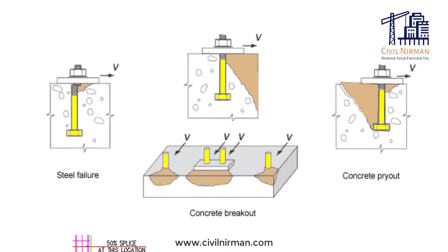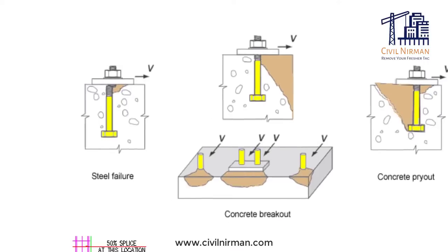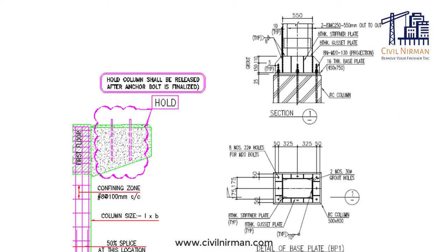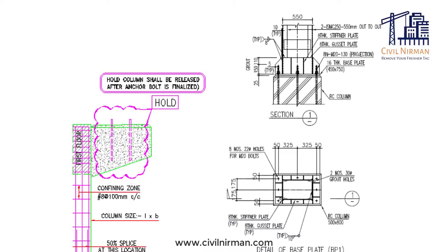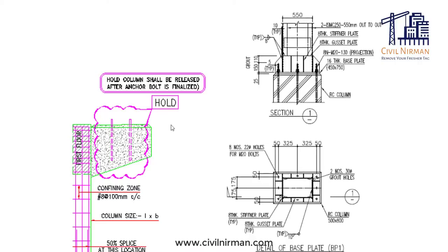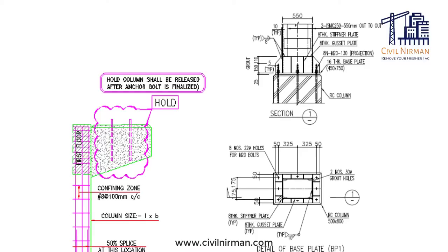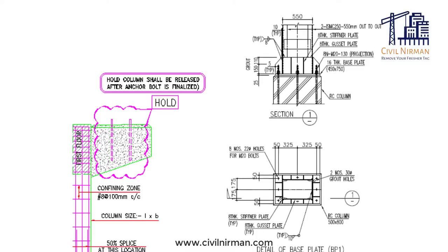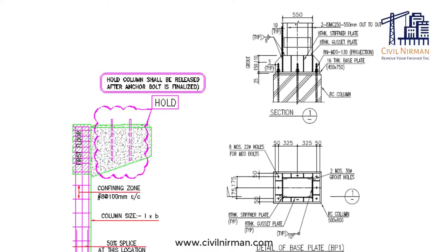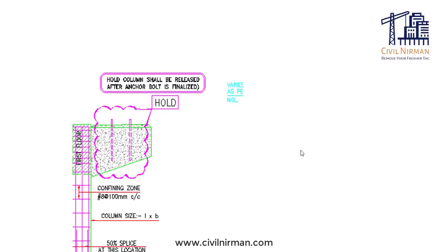So in the case of a steel structure, once you finalize your foundation design, after that you need to finalize your anchor bolt and base plate as well, right? Because after finalizing the base plate size, with the incorporation of a few edge security for the concrete, your pedestal size will be a little bit larger compared to your base plate size. So in that case you need to finalize your base plate first, and you have to keep that point in mind.